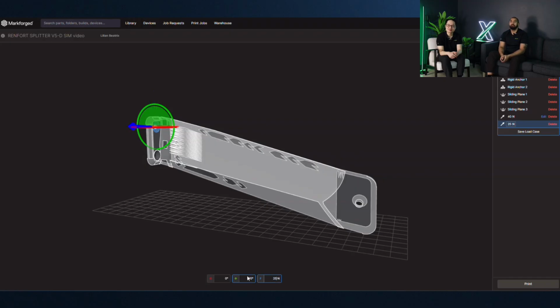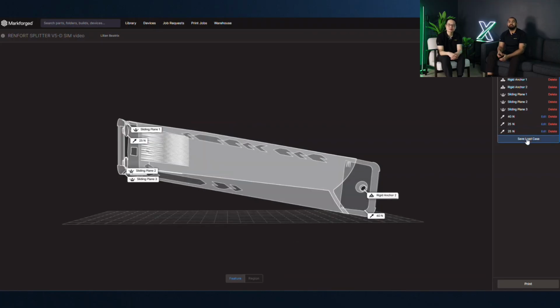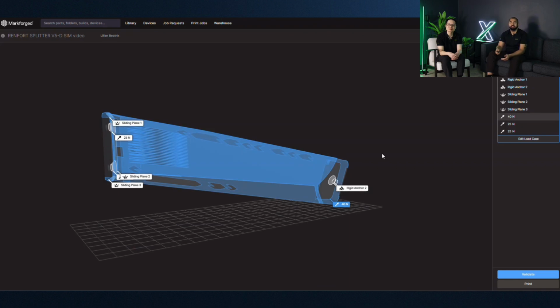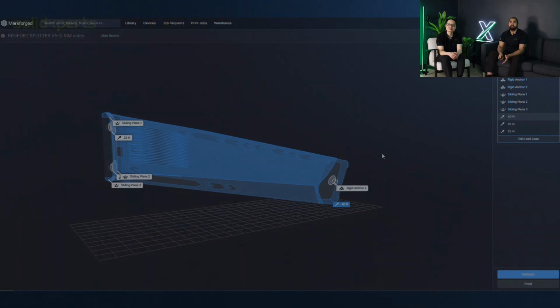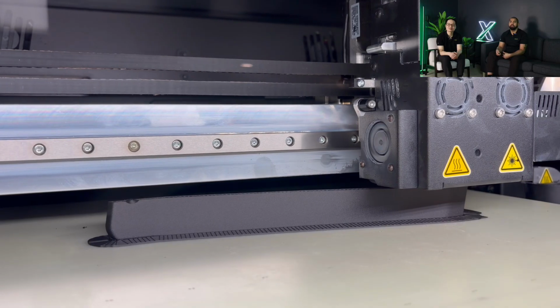The next step here will be to find the print direction for a part. As you might know, a 3D print isn't actually the same in all directions. Indeed, the height axis, the z-axis, will be weaker than the other 2 axes. This comes directly from the printing technology and the layer-by-layer adhesion versus within the same layer. So here, we're going to try to see what the best print direction would be to keep the weakness of the z-axis on the axis that is under the least stress. So we're going to run a simulation, specifically vertically, and compare it here with other positions.